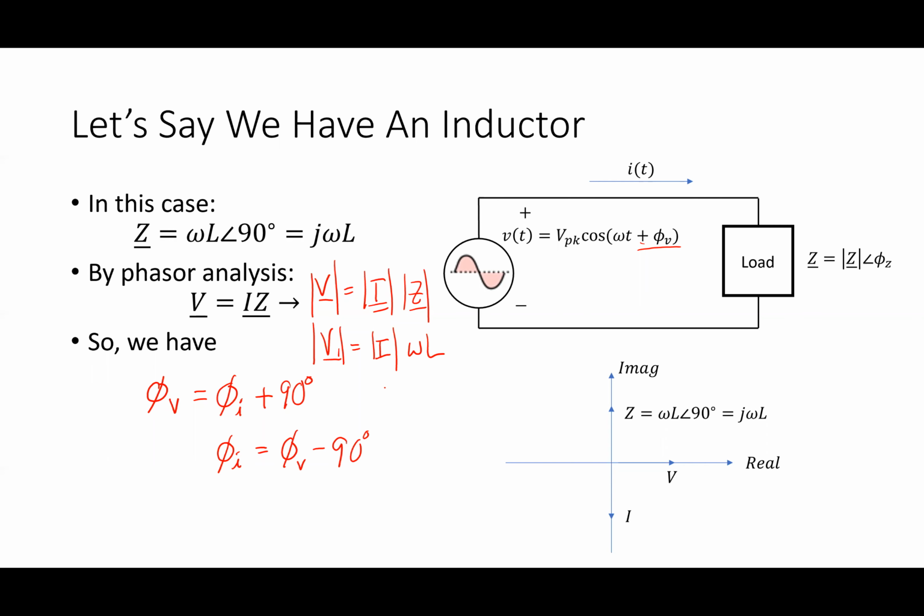In this case, I drew my phasor diagram here. I put a voltage phasor there. What's the angle for that voltage phasor? 0, right? My inductor has an impedance angle of 90 degrees, which means it's pointing up. I wanted to show where the current is. So if V was at 0, I is at negative 90, correct? It's 90 degrees behind, like this in my phasor diagram.